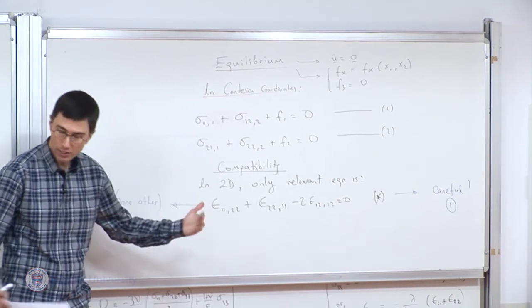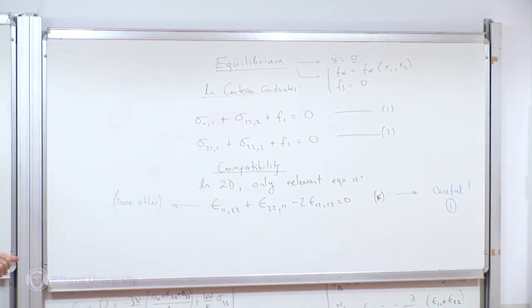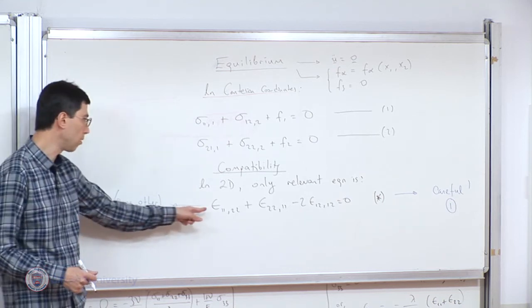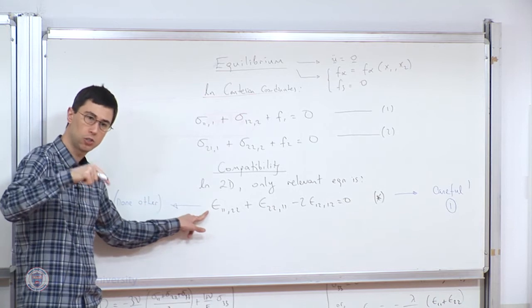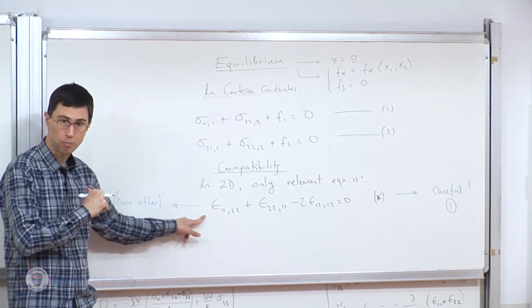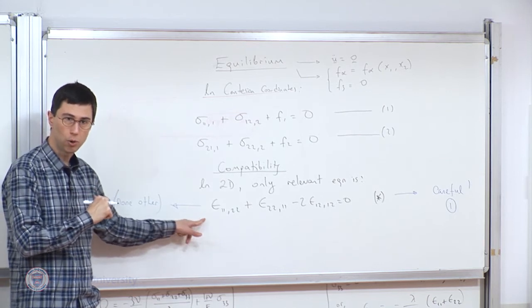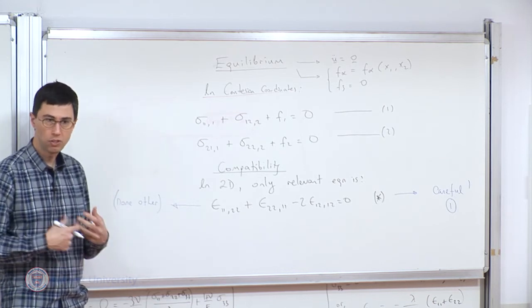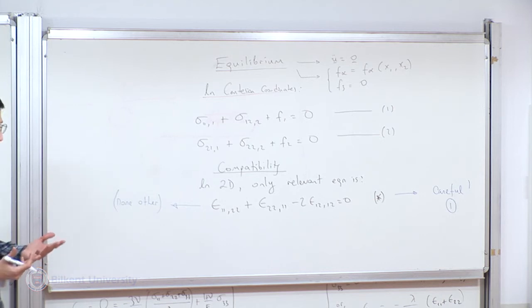Okay? It makes sense to cast it in terms of strain because eventually, if the strain satisfies compatibility, then I will try to construct displacement from the strain. But now I'm going towards a stress-based approach. In the stress-based approach, the variable that I have describes the stress. Now, once I have the stress, I can always write the strain like this.